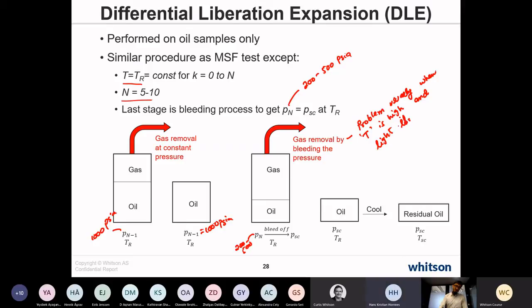And the reason for that is the light oil has more of its components in the light heavy range, C7, C8, and so forth. And the high temperature brings the K values of those components higher and higher, because you've got this K value versus pressure plot, and it's got this 1 over pressure dependency in that pressure range.